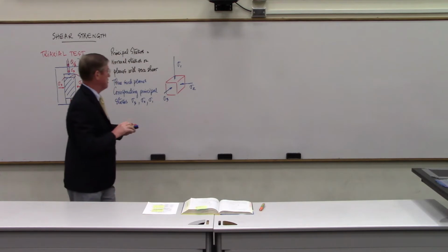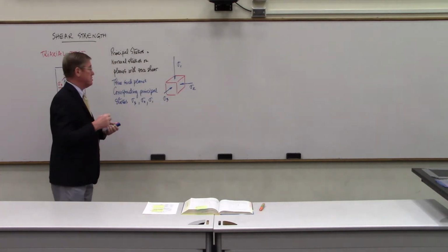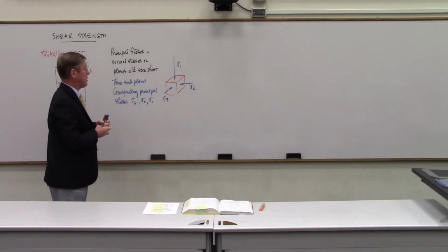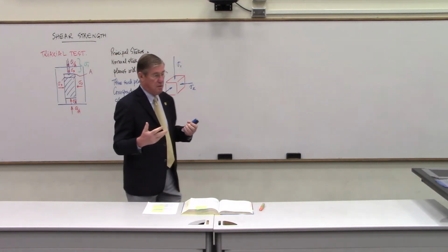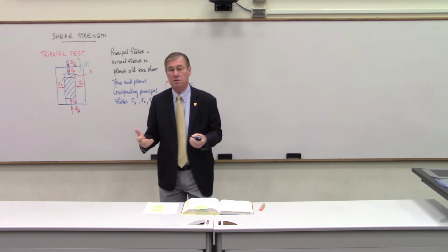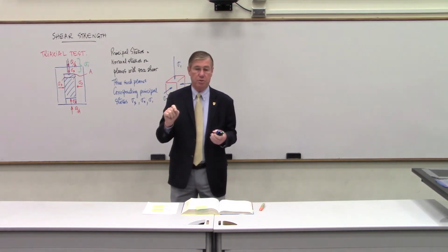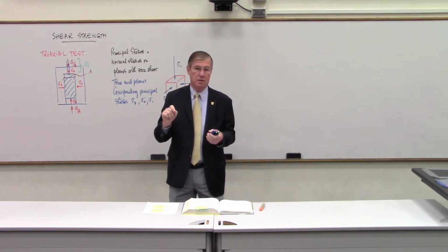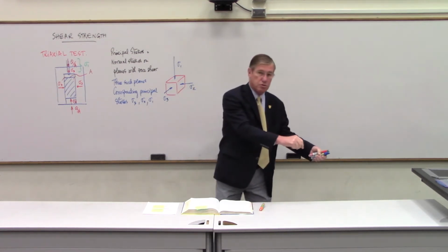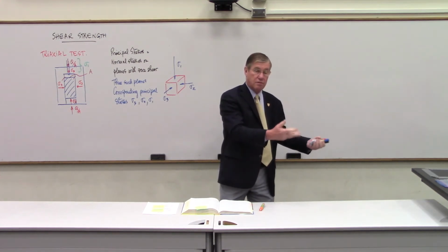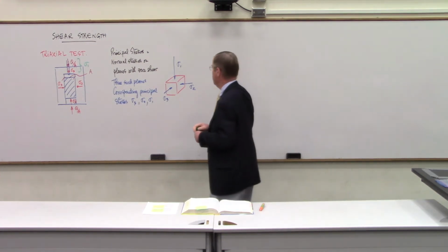So these are three principal stresses on three perpendicular planes, and these stresses exist under our feet right here in the soil. If you pick a point, the stress field at that point will be characterized by three principal stresses. If you move to another point, you have another set of different principal stresses.